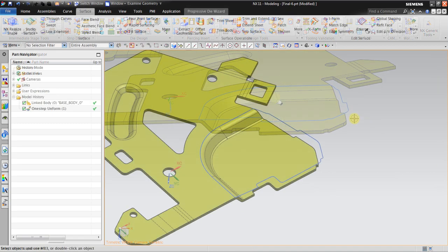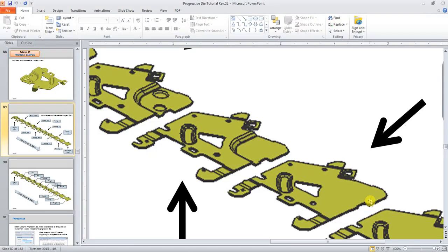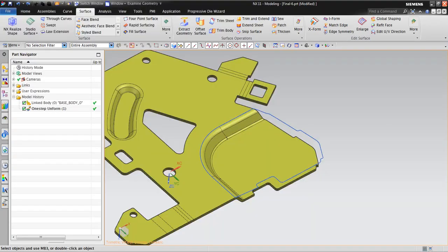Analyze formability creates this region of curve. So it means what I need to do now is to fill in the surface, and then I will extrude, trim body. I will remove this section, and the solid extruded from here I will unite with this part. So as you can see, the result will be like this.